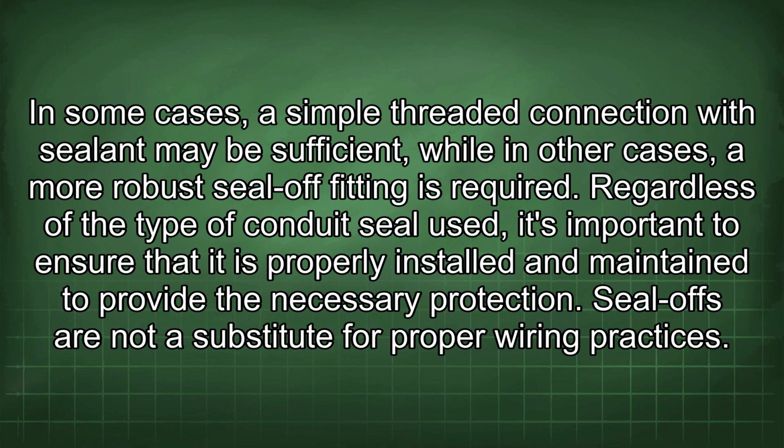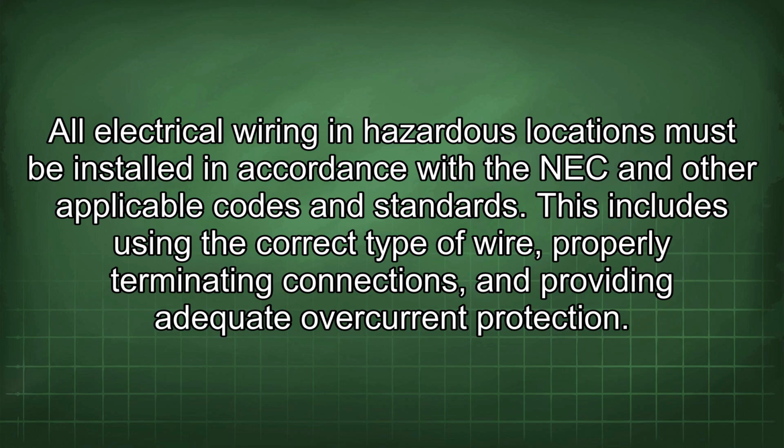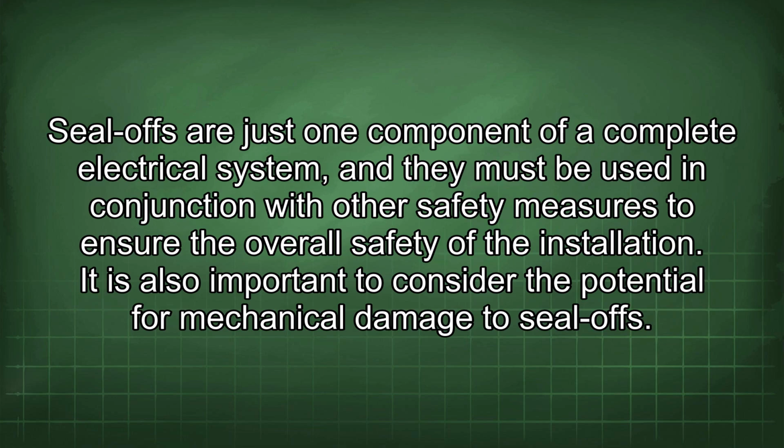Seal-offs are not a substitute for proper wiring practices. All electrical wiring in hazardous locations must be installed in accordance with the NEC and other applicable codes and standards. This includes using the correct type of wire, properly terminating connections, and providing adequate overcurrent protection. Seal-offs are just one component of a complete electrical system, and they must be used in conjunction with other safety measures to ensure the overall safety of the installation.